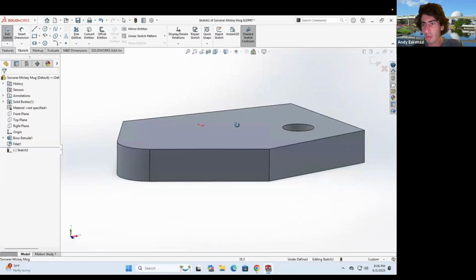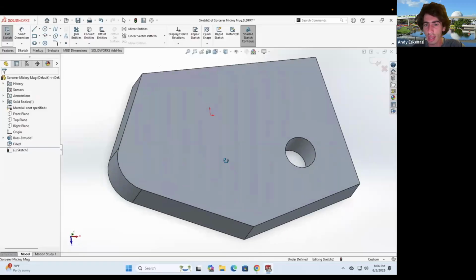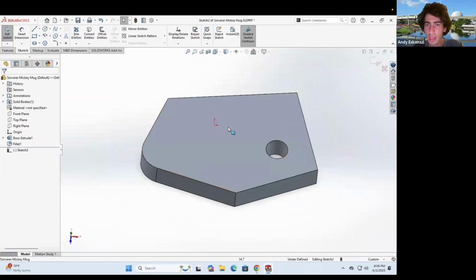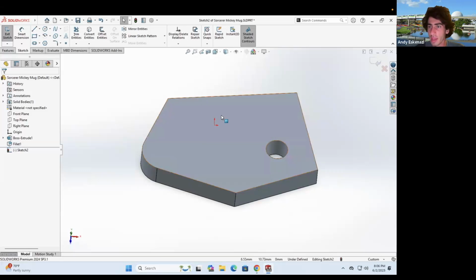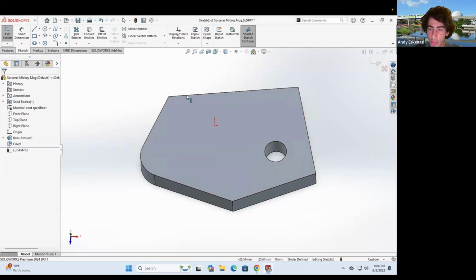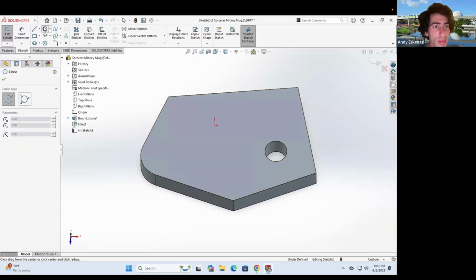And maybe you are wondering, how am I moving around like this, which is called the pan command. To pan, you can right click, and well, actually not in here, but if you look at your mouse, you have to press on the ball of your mouse. That's how you are able to pan around. And that's something important to mention. It's not trivial.